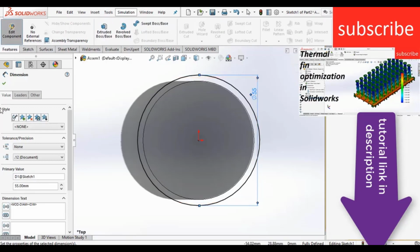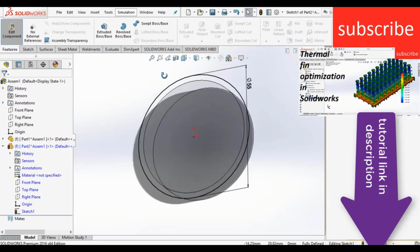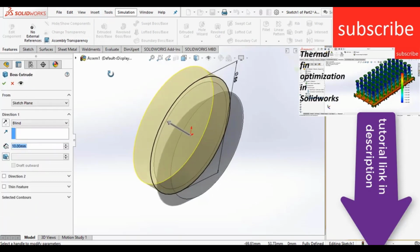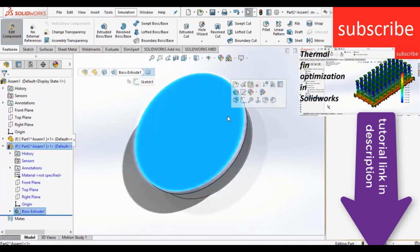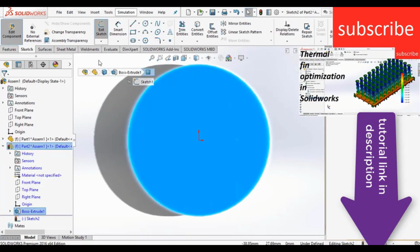My heat sink is bigger than the chip. It is not necessary that you make the heat sink bigger than the chip. It is up to you whether you want to make it smaller or bigger. So select the chip, reduce the thickness to 3 mm, click OK, and select the top face, click on sketch, and press Ctrl+8 for a normal-to view.